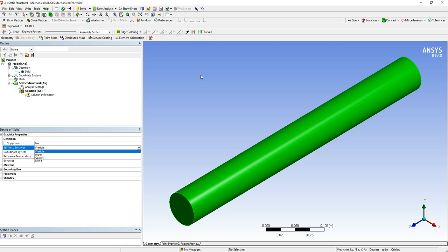So if we had another bar to hit it, but we made this bar rigid and the other bar flexible, when the two came into collision, the central bar would stay rigid. It wouldn't register a lot of the effect, but it would all be passed purely to our target impact bar. So we can centralize a real dramatic effect of what's occurring. You'd still get force transfer, but it would be centered more around the deformation of the main bar that we would be targeting. In our case, we're going to leave this flexible because we've only got one target in here.